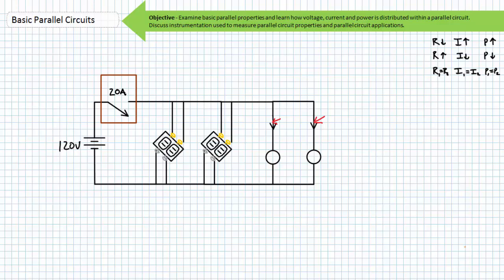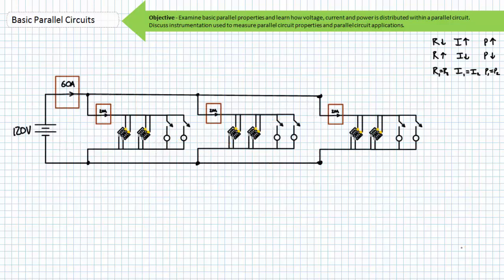Each item inside a branch circuit is wired in parallel, and stepping up one level, all the branch circuits with their circuit protection means are wired in parallel with one another. The main breaker services the whole residence. Each single breaker services one room or one subsystem. Additionally, residences can feature a sub-panel, for example, feeding a garage that connects or disconnects all branch circuits inside the garage only with the main supply.